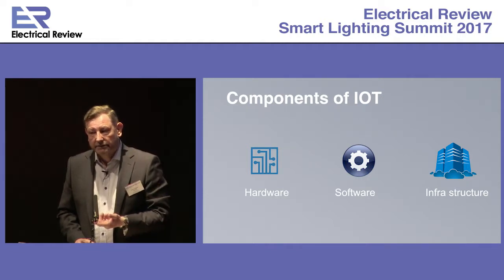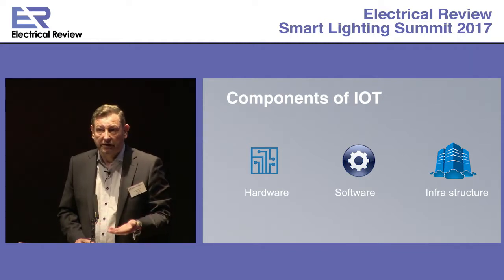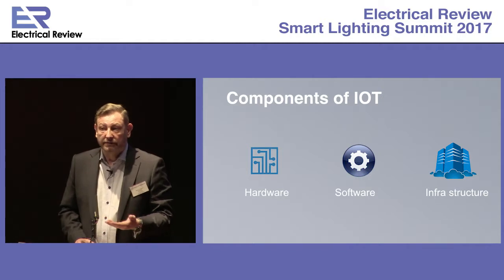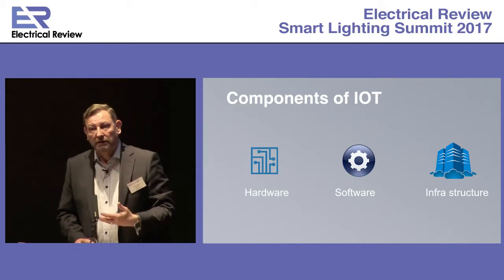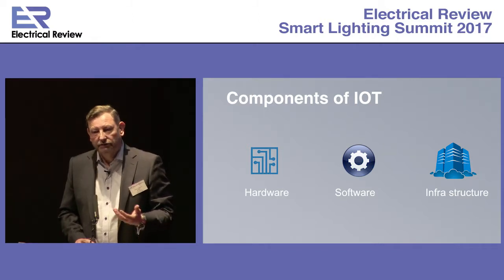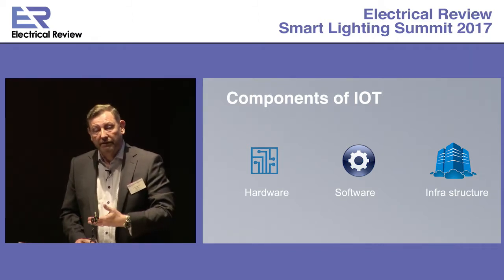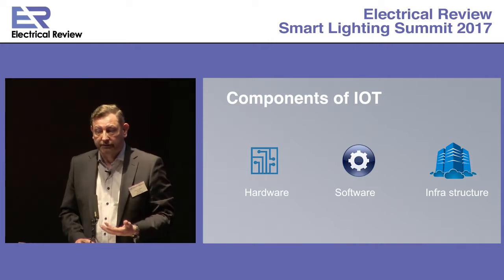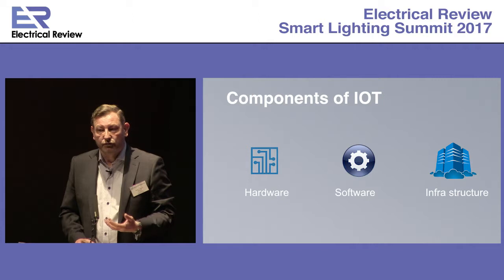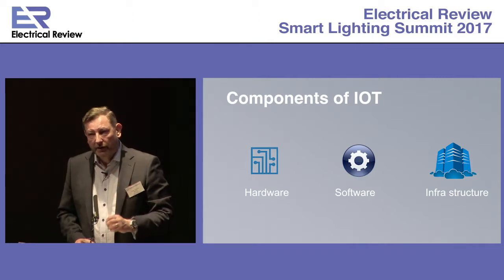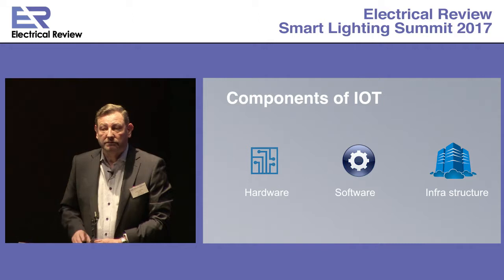Now, in practice, the only standard really for lighting is DALI, because it's the only one that determines how you can turn it on, off, dim up, dim down, but it's a protocol, it's not a system. Linking Bluetooth allows you to expand that to give you greater connectivity, but it's not a Bluetooth system. At the back of that, you have to have a framework, an infrastructure. And that infrastructure can be anything you like. It could be KNX, it could be 6LoWPAN, it could be an IP network, whatever you choose. Now, this is where the problems come. This is where it becomes challenging, shall we say.